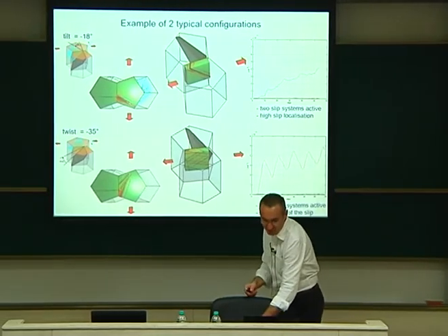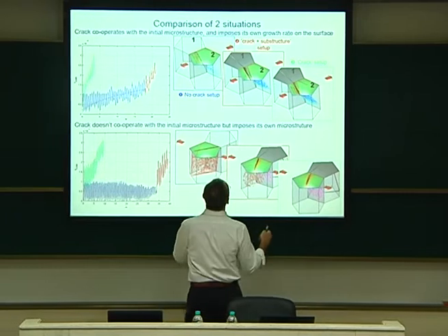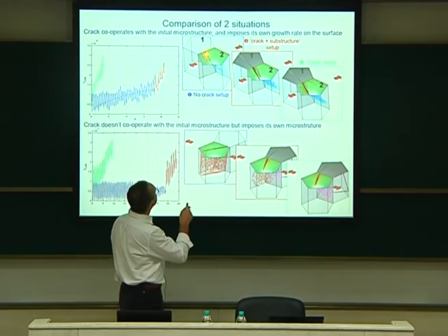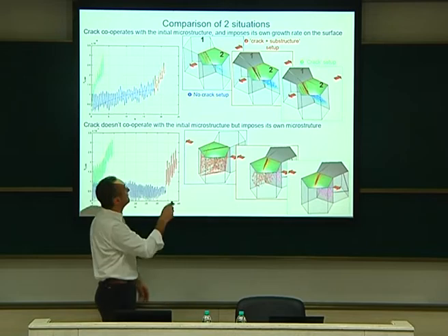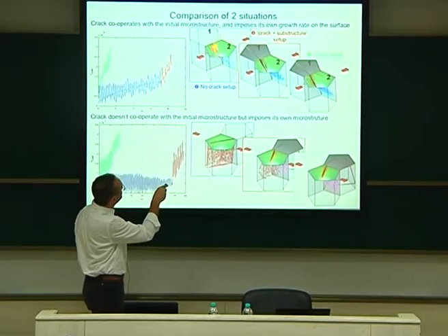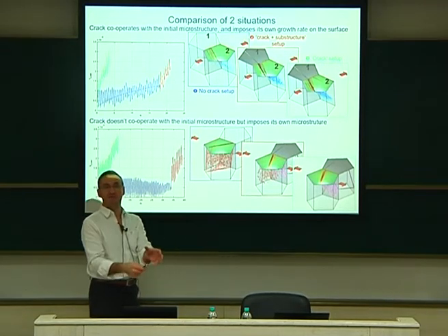Maybe this one is not the best example. Maybe this one is better. I would say that here, for example, where is it? Yes, here. You see, we load in fatigue. This is exactly what I showed yesterday. You can see your persistent slip band here, the blue plane, and this is the extrusion here. This extrusion follows exactly the principle as yesterday.